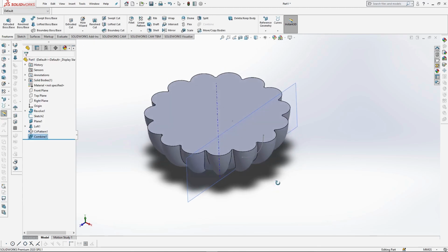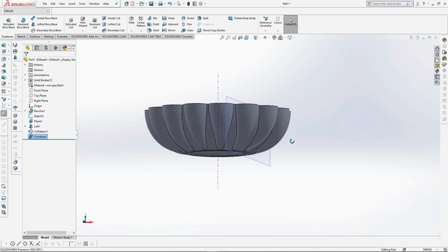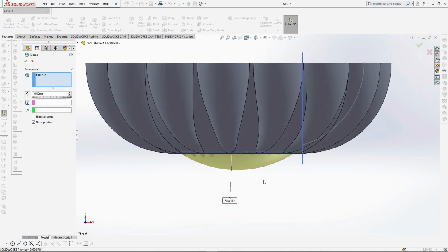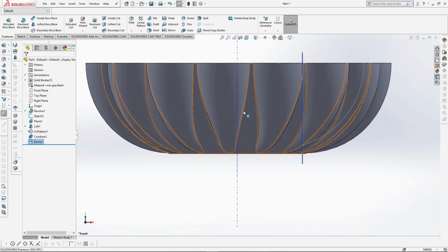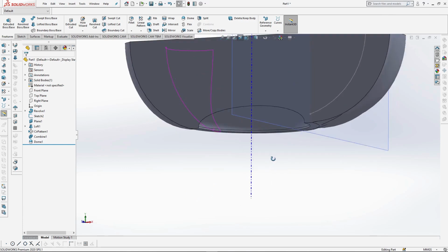The design of this bowl is to be flower-like, so the next part of the design is the centre of the flower. Selecting the inner bottom face of the bowl, I'm using the Dome tool. I'm reversing the direction of the dome to make the face dome inwards. Keeping the dimensions at 10mm, but ticking the elliptical dome box to get a less circular profile. OK this feature.